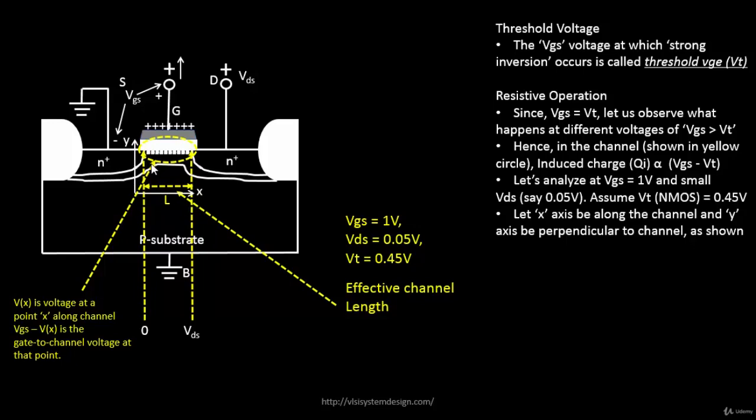So that's why I said a voltage gradient over here. It goes from higher voltage to lower voltage. So channel voltage is not constant, it's a gradient. There's a gradient over here because of the presence of VDS. If this was grounded, this was all constant.